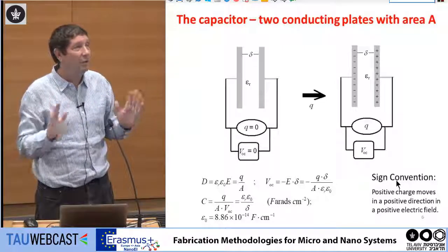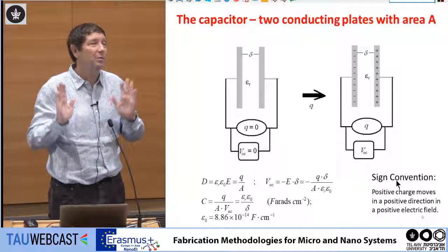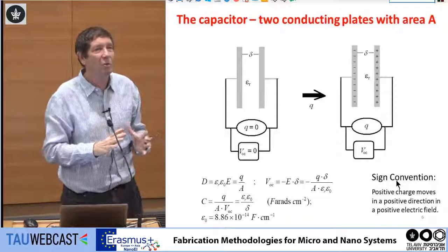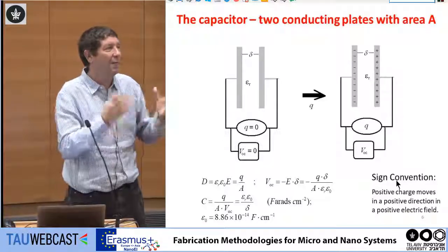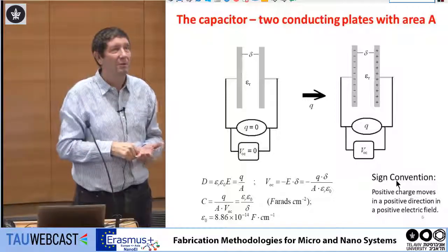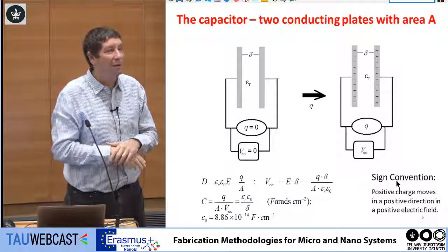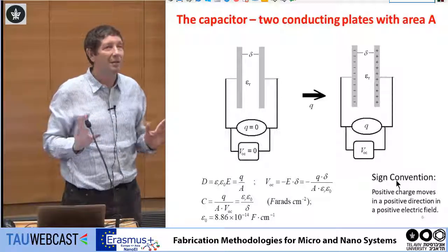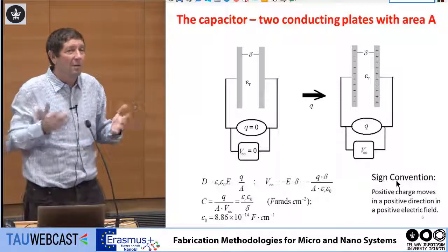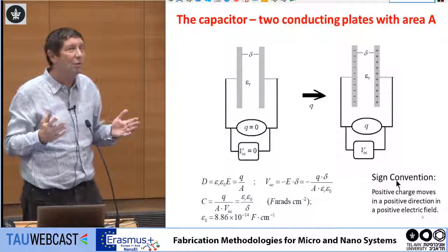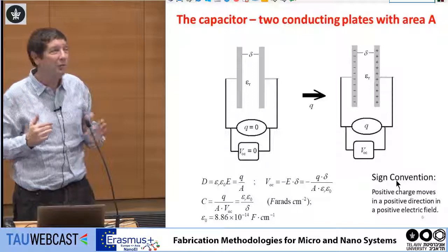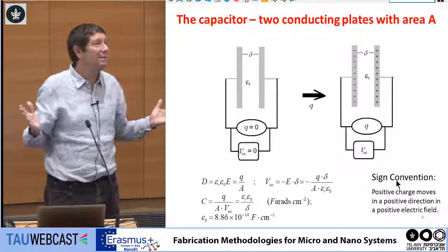So far, nothing new. Now, you do the same experiment in air. This is what you get. Now you take water and put some sodium chloride, some salt inside, or take some blood, or take some electrolyte, and put this inside the electrolyte. You see that the capacitance changed dramatically. It goes up by orders of magnitude. What happens? The dielectric constant of water is like 80, so it should increase by a factor of 80, but it's not. It's much, much higher. And also, it becomes independent of the distance between the plates.